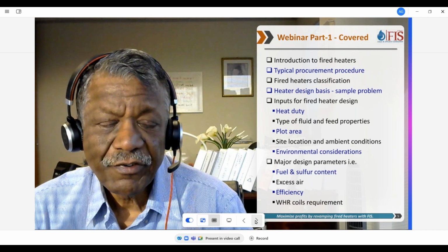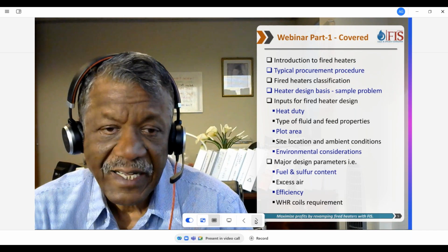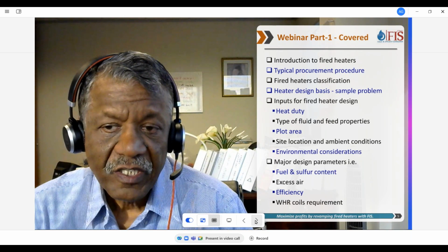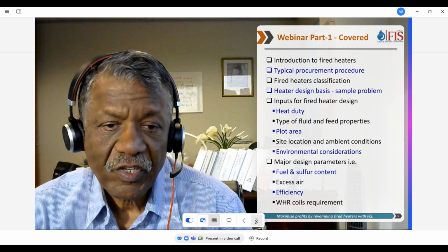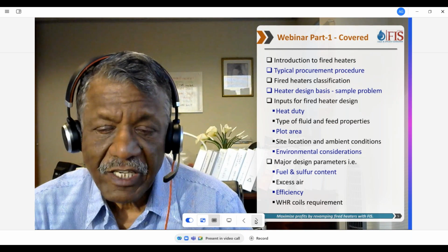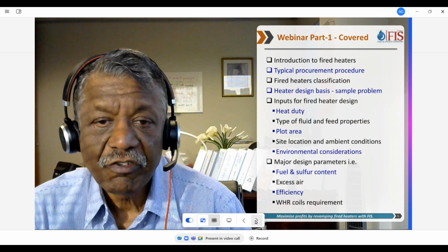like fuel, what fuel you are firing, how much sulfur content it has, because it does affect the efficiency and corrosion. Then how much excess air, what type of efficiency are you aiming at? If you have any requirement for waste heat recovery, those can also be specified.